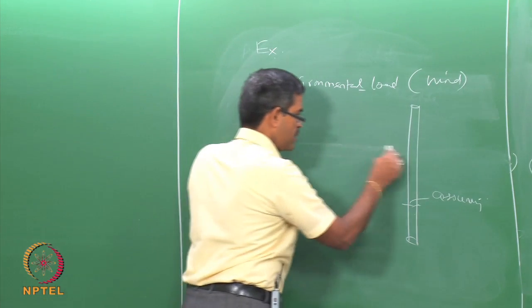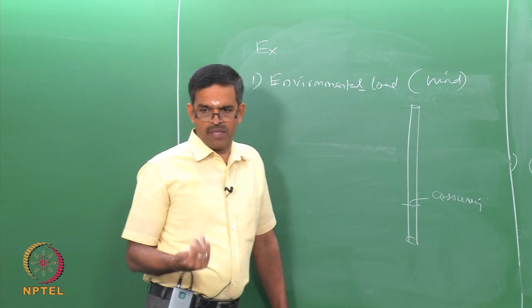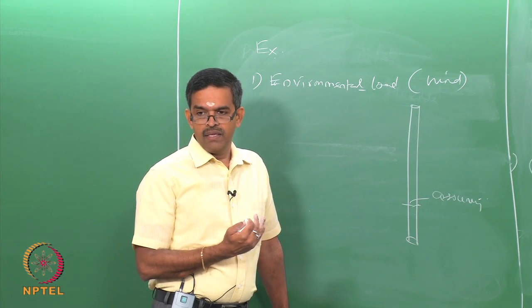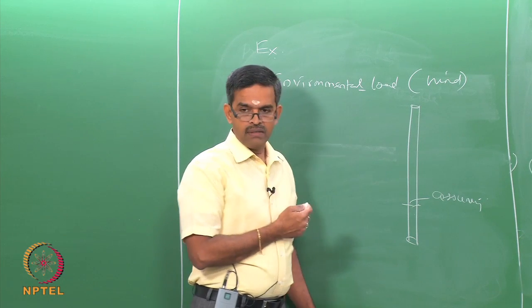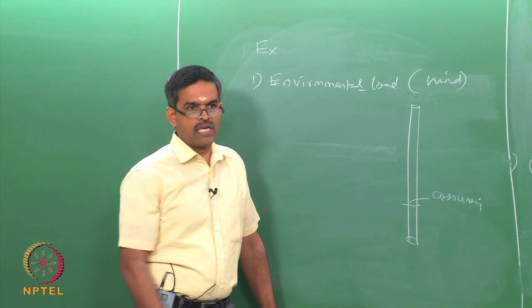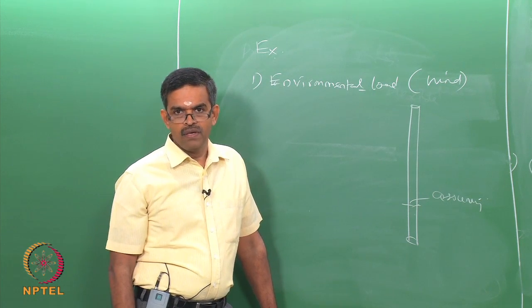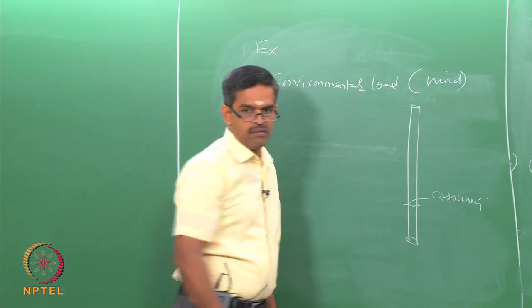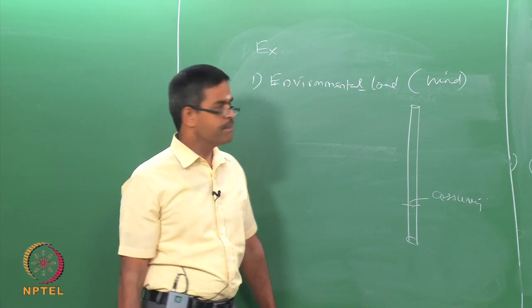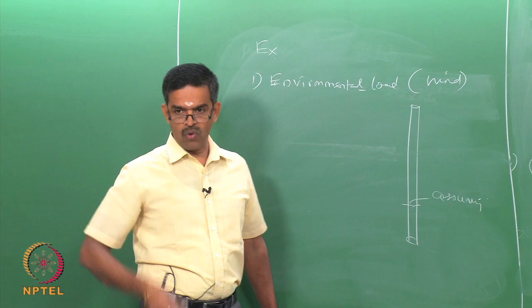If you have a doubt, let me explain this. Wind force is actually a generation from the pressure which is proportional to the projected area. The projected area is of course a function of the diameter if it is a circular member. So, you have to assume the diameter of the member. When you assume the diameter based upon your engineering expertise, experience, etc., you want to compute the force.